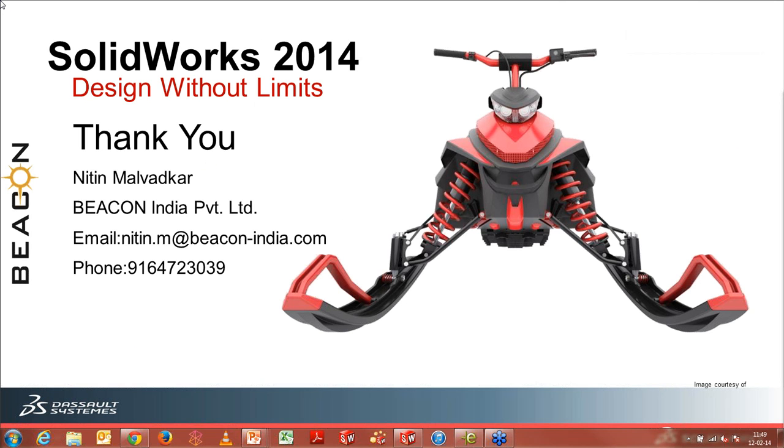There's one question over here which says, while deleting the parent feature and retaining the child features, does the child feature become dangling since it has lost the dependency from the parent feature? And can we redefine this child feature later? Yes, that is something which we can do in SolidWorks 2014.